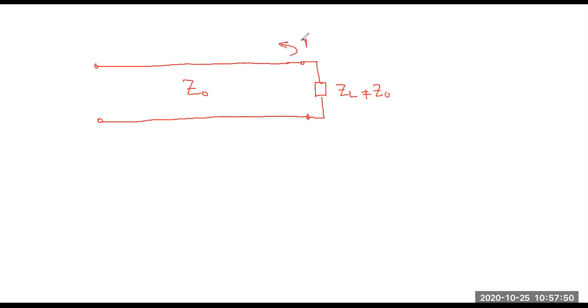So this is our main transmission line. We have the original problem: our transmission line with characteristic impedance Z0 and our load ZL not equal to Z0. As a result, we have an impedance mismatching problem, reflection coefficient not equal to 0. And we want to solve this problem with the help of double stub. So what are the two possibilities?